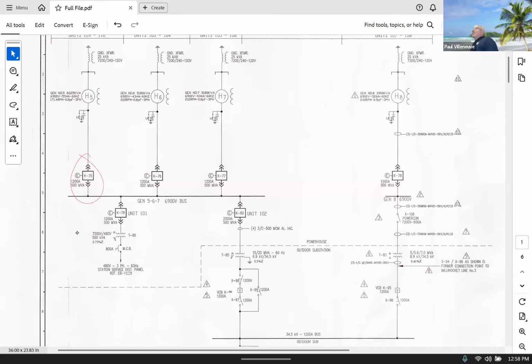Those don't have any impedances, right? I mean, a breaker should just be a short circuit or not a short circuit, an open essentially. So when you're drawing an impedance diagram, you wouldn't include any breakers on it because there is no impedance. It's an impedance of 0.